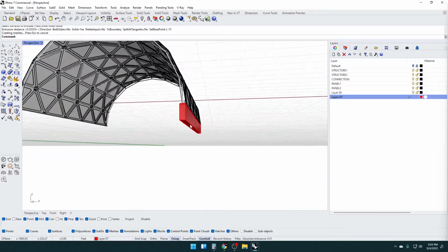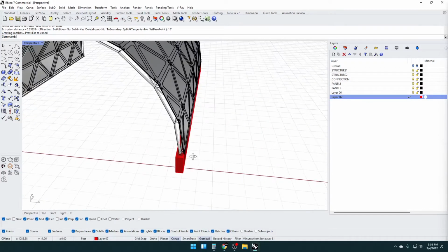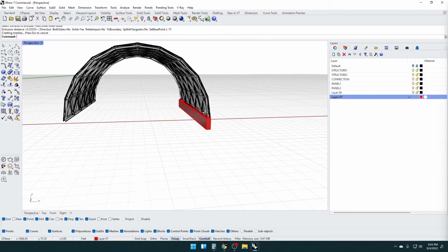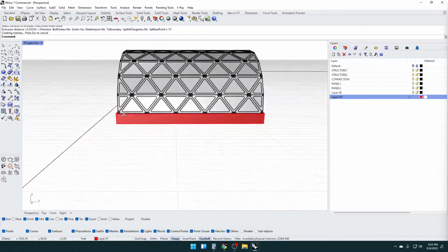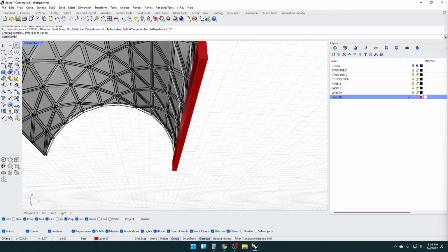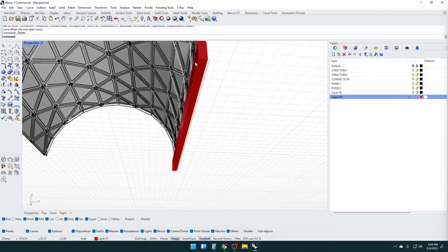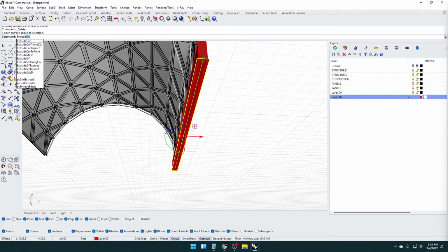Either way, without a person, you couldn't really tell the scale anyway. So this might as well be, you know, 6 inches and this be 10 feet tall, or this could be, you know, really, really large. So that's that stem wall here. And then we'll use the center line to offset for a footing. So we'll offset 4 feet this way, 4 feet this way. We can loft these, we could extrude it, different ways of doing it, and then extrude surface.